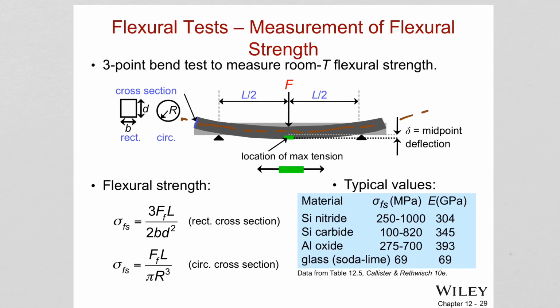Based on that information, the moment, the neutral axis distance, and the moment of inertia, which is based on the cross-section, as I said, because depending on the cross-section the stress levels will be different. So all these parameters are included when we are calculating the strength, and that is where these equations come from. You can find more information in your book, but not more than this is necessary.